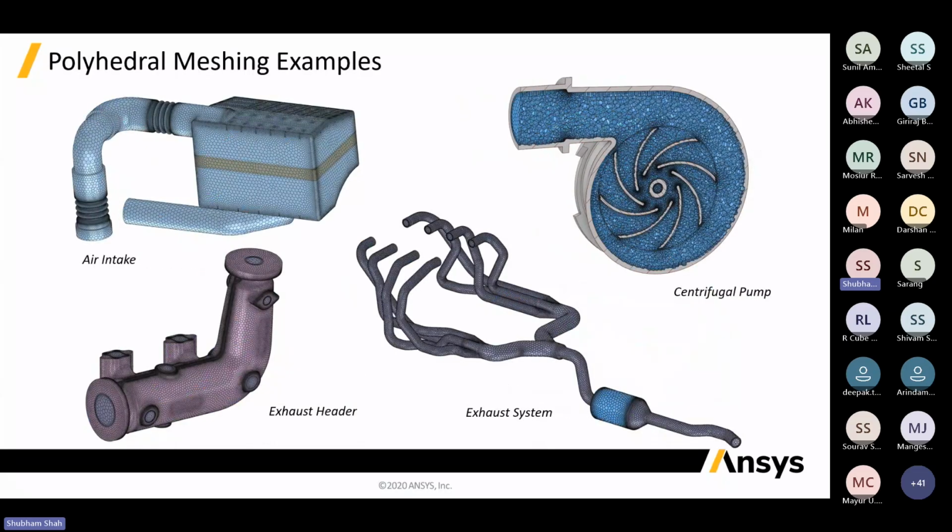These are a few of the examples for the polyhedra meshing. Ideally before this version, the polyhedra mesh was only available for Fluent, which is for the in-depth physics simulation. But now this polyhedra meshing capability is also added to Discovery simulations. So we have the control of meshing in Discovery for the CFD part, only in the refined mode.